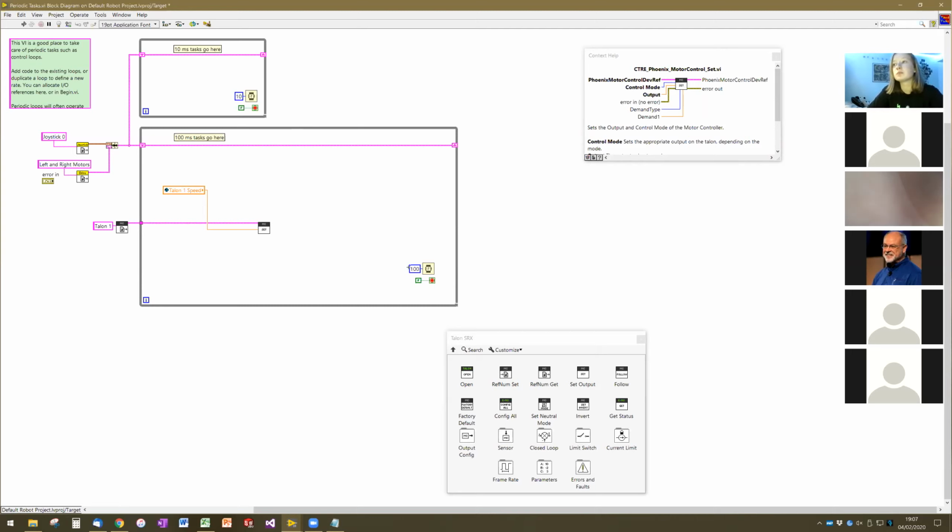Yeah, it can. The CAN bus has a certain amount of data that it can have on it at any given time, so there's a certain amount of bandwidth. If you send the commands over and over again, you can use up all the bandwidth and start to get lag between your controllers. That's one of the issues that the other architecture type solves.